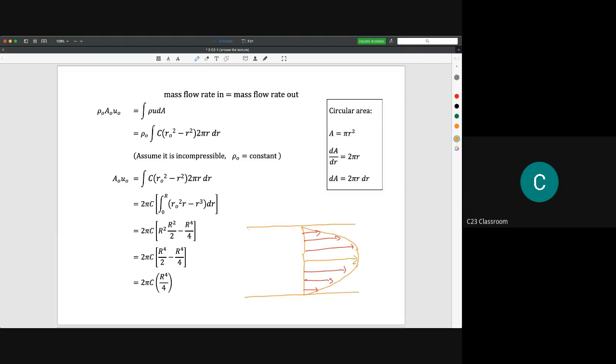Okay, this is the velocity, and normally we take one small area here, for example. So we need to calculate what is the mass flow rate for this small area here. And then to get the total for this velocity profile, we need to integrate this function. This function means to integrate the function for this small area.